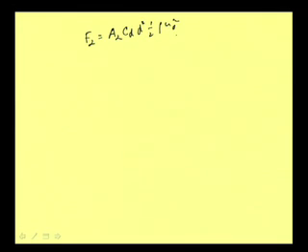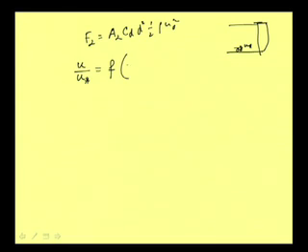From that, if we see that we have already one relation that we analyzed, that is the velocity distribution. We are interested to know what will be the UD at this level. At particles like this, what will be the velocity UD at this level, and we can take help of our understanding of the velocity distribution, and that we had that U by U star. Already we have discussed that in our last class. This U by U star is a function of shear Reynolds number, that is nothing but U star d by nu.